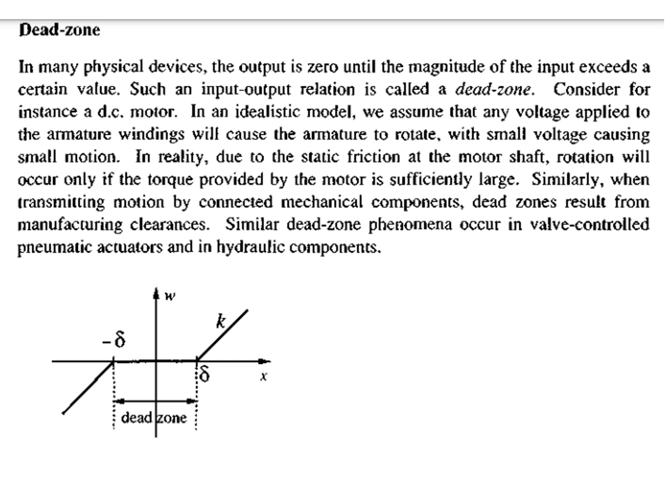So dead zone. As I hope in the first unit we studied about dead time. Dead time is the time for which the output takes some time to respond to the given input. Similarly, dead zone is the period within the tolerance band, that is minus delta to plus delta. If you take this dead zone, the element will remain dead, that is, it doesn't respond to the given input.